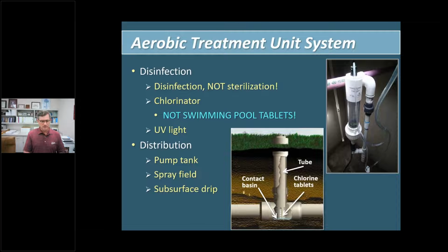And a lot of times what I've found, the tabs may look the same. Sometimes there's a difference in diameter and size, so how they fit. A lot of times your chlorine tablets will swell and stick, whereas your true wastewater disinfectant tablets will not. UV can still be a process for